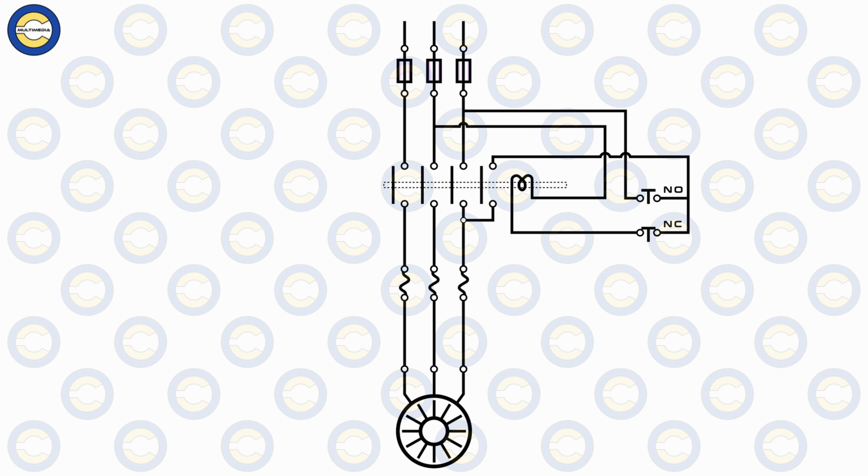Because there is no back EMF generated initially to oppose the applied voltage, this results in low effective impedance and hence a very high starting current being drawn. This is further compounded by the fact that in induction motors there is higher slip and low inductive reactance at the starting of the motor.